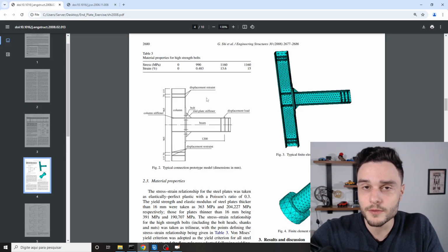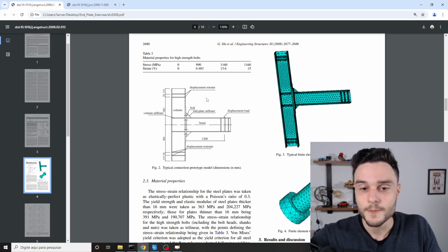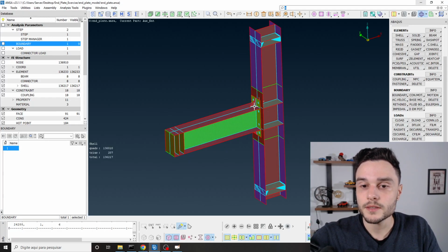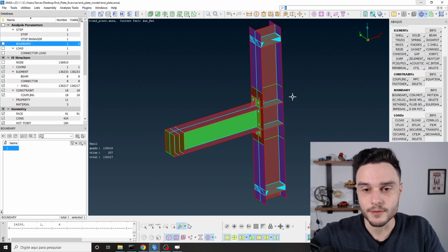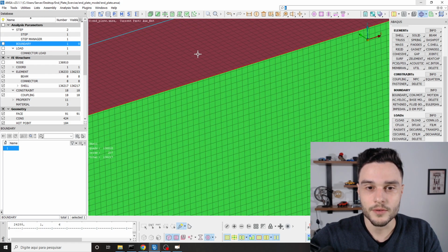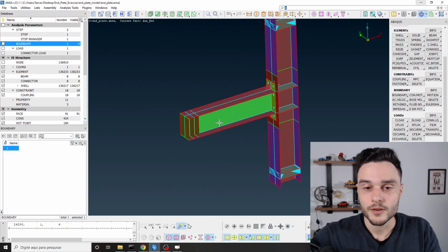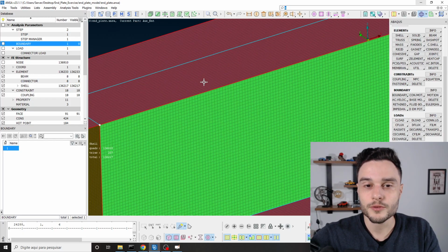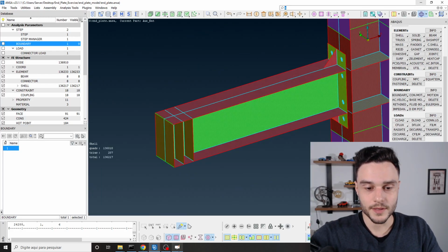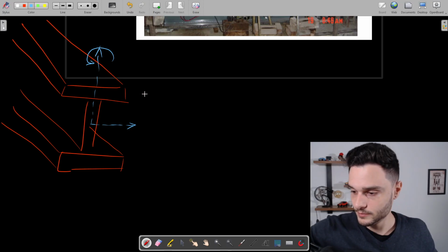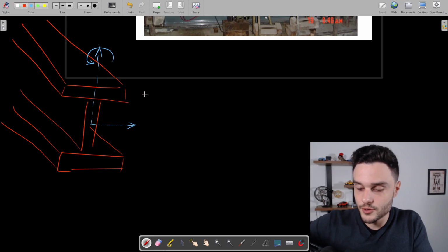Maybe we could even simplify this by not applying gravity, but let's apply gravity because we are going to learn how to do this and it's interesting. So natural boundary condition is related to traction and body force. Remember that traction is a force per unit area that we apply on an outer boundary of the domain, right? Traction could be, let me get here and create this drawing.